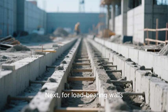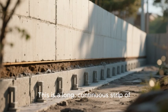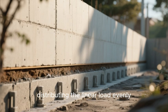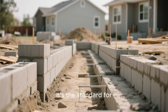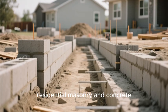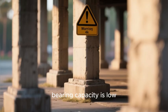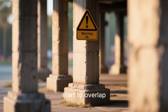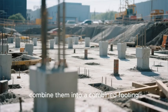Next, for load-bearing walls, we use continuous strip footings. This is a long, continuous strip of concrete that supports a wall, distributing the linear load evenly along its length. It's the standard for residential masonry and concrete construction. When columns are too close together or the soil bearing capacity is low, their individual isolated footings would start to overlap. The efficient solution is to combine them into a combined footing.